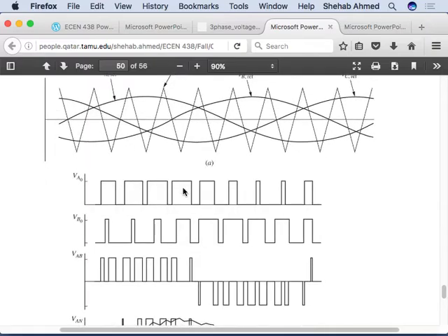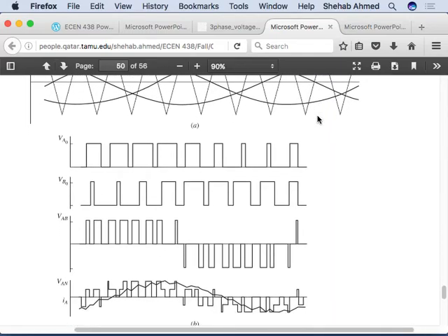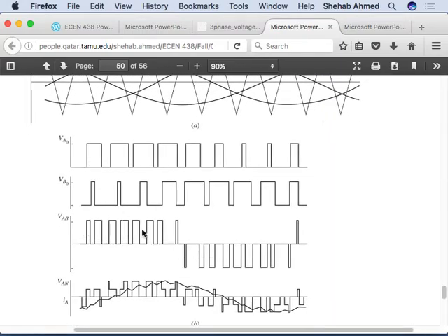We discussed that for the single-phase inverter, and we discussed it at the beginning for the three-phase inverter. Here they just show you that this is the carrier. The triangular is my carrier waveform, and I'm intersecting the 3 duty ratios: VA reference, which is my duty ratio for phase A; VB reference, duty ratio for phase B; and VC reference, duty ratio for phase C. Right? So what do I get? At the output, my line-to-line voltage is something that looks like this.